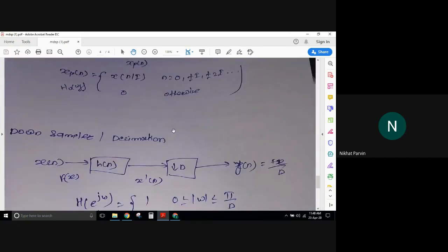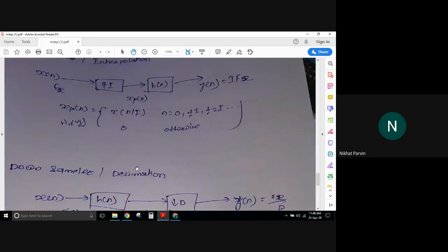They'll be giving a heading in your exam to explain interpolation and decimation. So first you have to start by talking about upsampling and downsampling, and then interpolation and decimation. Earlier I talked about only upsampling and downsampling. Now you are allowing the signal to pass through the low pass filter, before and after that, giving the interpolation and decimation factor.